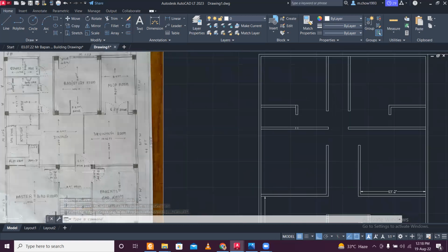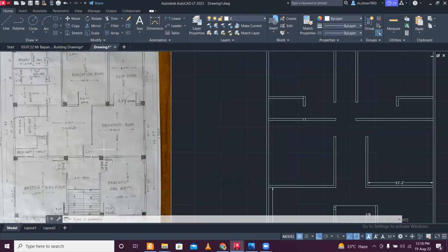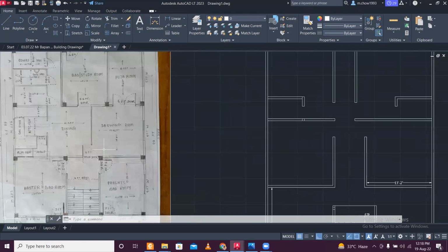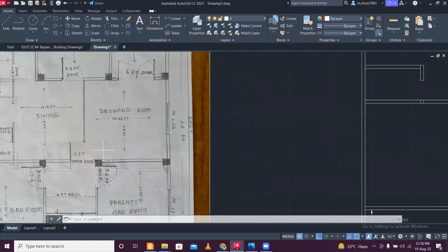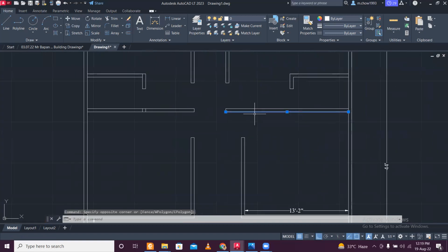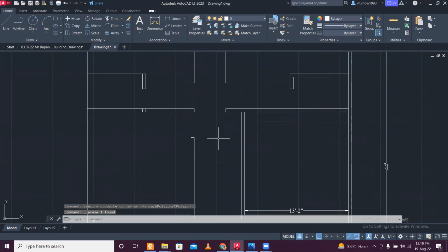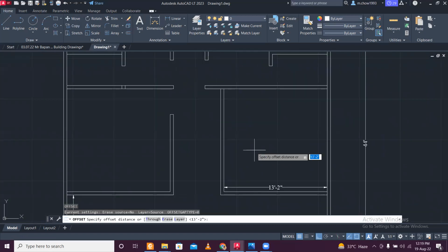Okay, drawing hall, but obviously they want the entrance to here. This is interesting. They want the entrance to here and don't want this drawing room to have any door. Okay, I kind of understand this. So I'll just select this, EX enter, do this, and join this, and maybe I'll leave a 4 feet space from here.